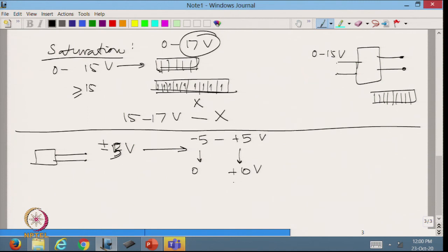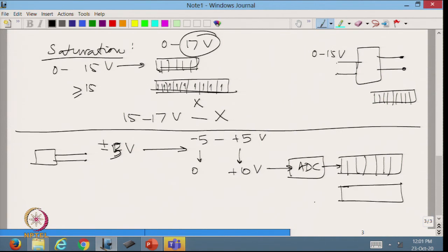We just do a simple addition, put this into the A to D converter, and after that interpret that digital data by saying that I added 5 volts to it, and now I subtract it to get my real number. So, that is the other thing we do. This is another aspect of ranging, where the other one we saw was the multiplication part of it. Then we also saw that we should not be restricting ourselves to only a few bits of the A to D converter; we should try to use as much of the range as possible.